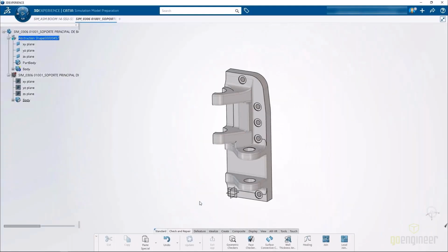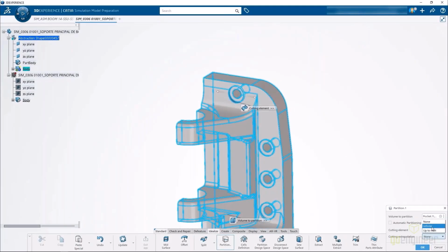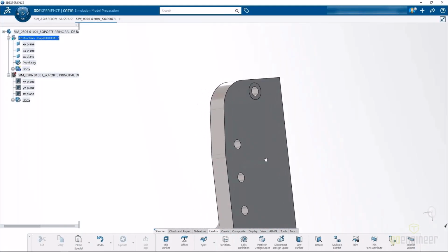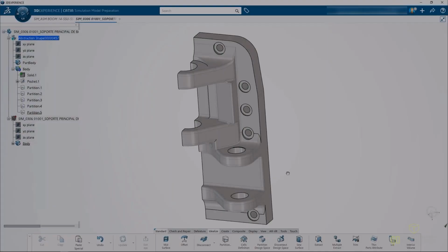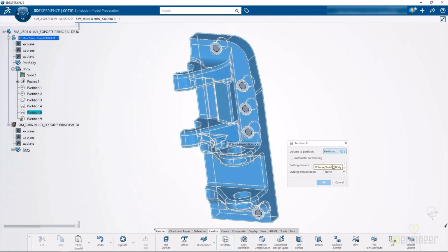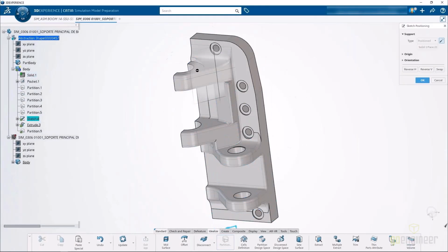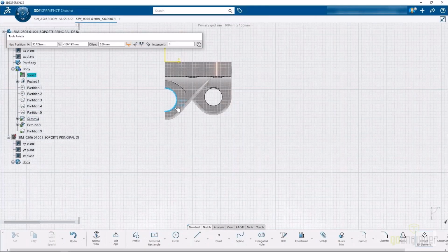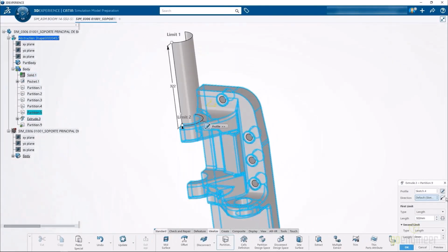Additionally, we can partition sub-regions of the CAD model to allow for easier meshing with hexahedra elements later on. It's quick and easy to use familiar modeling techniques to split the model up as much as you wish, and then simplifying the model and allowing for more robust meshing techniques will save a lot of time down the road.